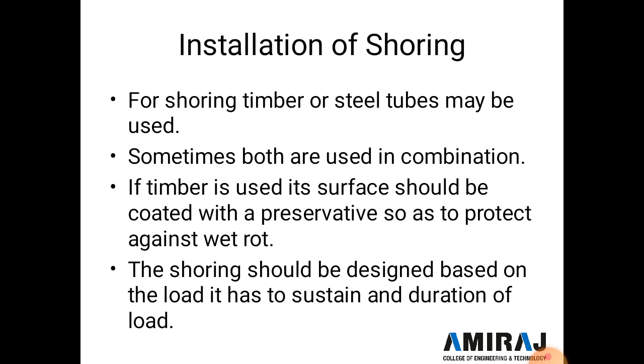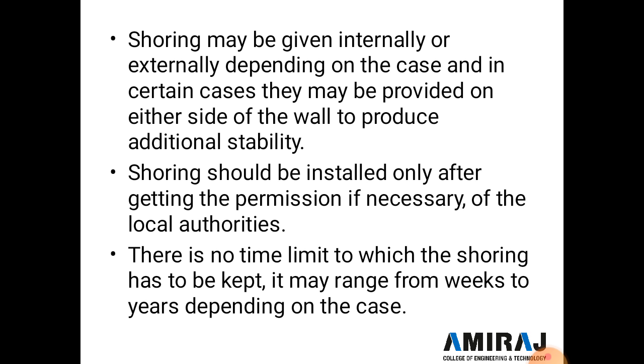Now if timber is used, its surface should be coated with preservatives so as to protect against wet rot, and the shoring should be designed based on the load it has to sustain and the duration of the load. Now shoring may be given internally or externally depending on the case, and in certain cases they may be provided on either side of the wall to produce additional stability. Shoring should be installed only after getting permission, if necessary, of the local authority, and there is no time limit to which shoring has to be kept. It ranges from weeks to years depending on the case.